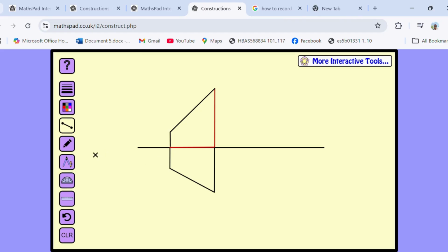Now in next step, I am going to rotate this line. So I am going to draw an arc with a center, this one, A prime, and radius A prime B prime. So to do so, I use compass. You can also use compass. So you can locate the needle here, and this is your radius. Now make an arc. Length of arc is not important here again.